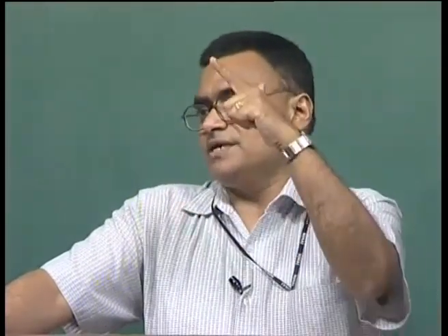All right. In McCabe-Thiele methods, we also have the same approach. Now we wrote down the operating line balance until we realized that the composition y equal to 0 corresponds to your xW. Earlier, when we didn't have an open system, we had a closed system. We had only one product leaving the envelope of our calculations, and there we had xW equal to yW falling on this 45-degree line from which we connected.